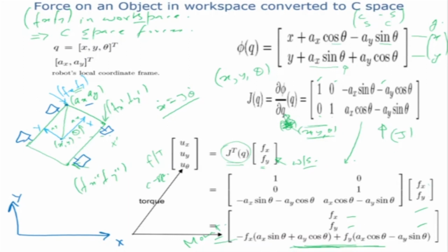Now suppose there's an obstacle here. This obstacle is applying a force Fx, Fy at this point. Let's call this point P. This obstacle could be applying a force on other points also. So this is another force, let's say at P dashed. It could be applying some other force on that point P1 or P dashed. What I can do is take all these forces Fx, Fy acting at point P, convert them to torque, take the force acting at P1 or P dashed, convert that to torque